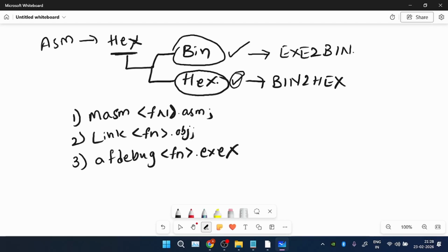This command we are not going to follow in the case of the stepper motor, because we need a hexadecimal file. Instead of this, we are going to use the command exe2bin: executable file to bin file. Type the file name in its exe form, space, file name in its bin form.